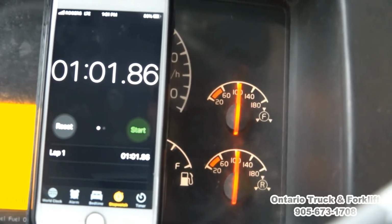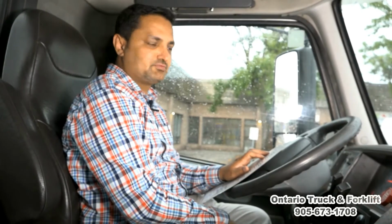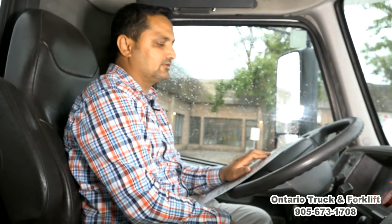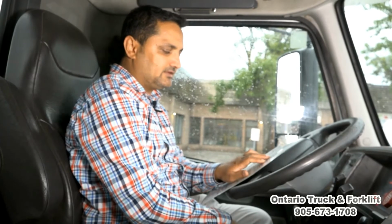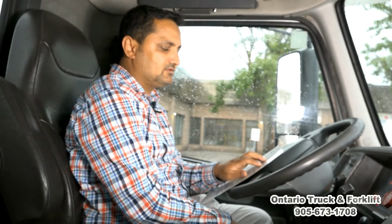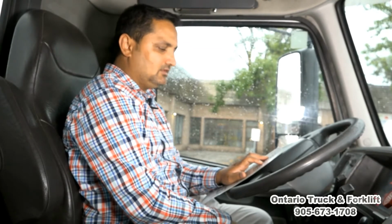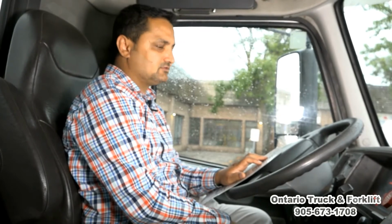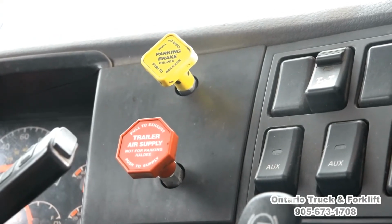Now we have to read Schedule 1. Audible air leak is a minor defect. If we have a minor defect, we'll call our owner, write it in the logbook, and we can drive the truck. Air loss rate exceeds the prescribed limit is a major defect. If we have a major defect in our vehicle, we have to call our owner, write it in the logbook, and we cannot drive the truck.